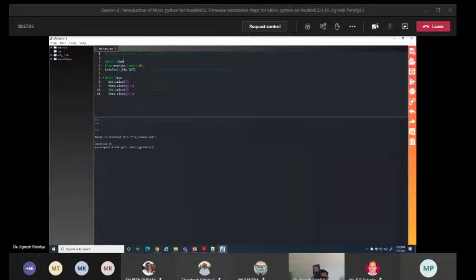But what happens once you deploy this NodeMCU in your AC and you are using this MicroPython to develop this smart AC application? Then each and every time you would have to click on this download and run button. So again, keep in your mind, during development this Python file name .py is there, but once we want to deploy this application permanently inside this NodeMCU, at that moment our file name should be main.py.